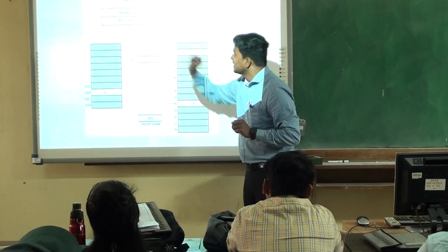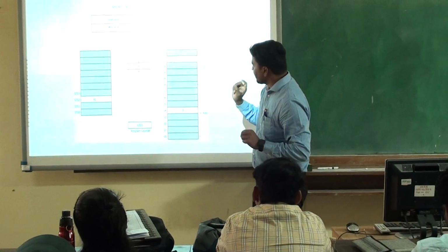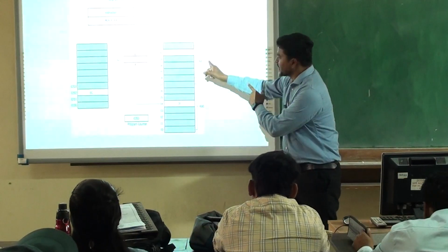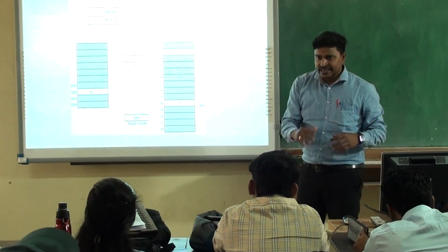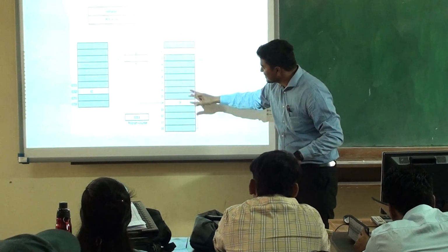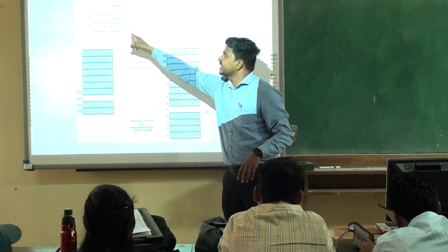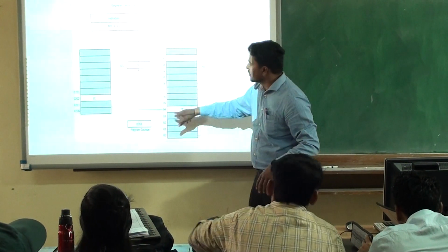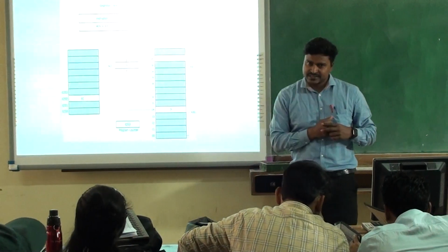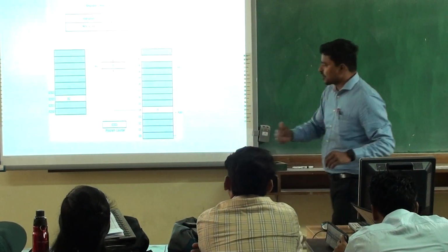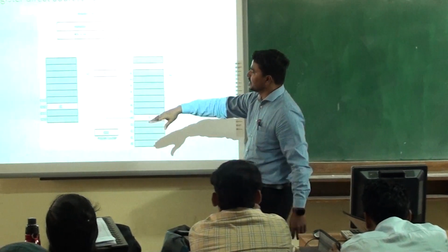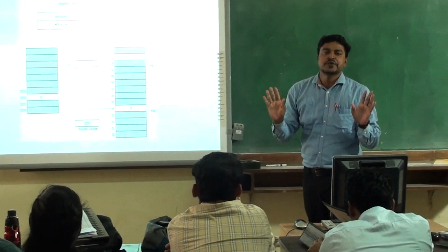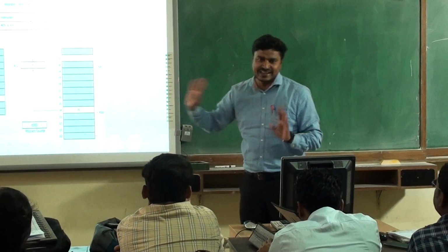When we write this instruction and it gets executed, what will happen? You can see this is called the register bank. There are 4 banks, bank 1, bank 2, bank 3, bank 4, and each contains 8 registers. Since we are putting R4 here, it will go to location 04, and the data 1F is there. After execution it will be transferred to the accumulator. The program counter will stay at the same point because we are not doing anything with program memory. This is data memory, and this is your program memory.